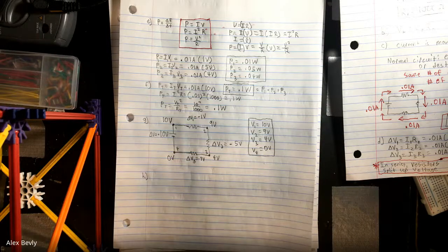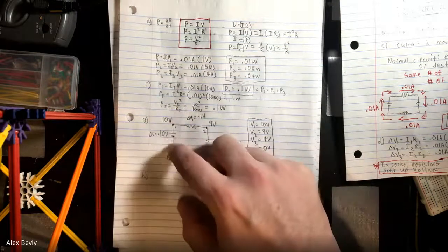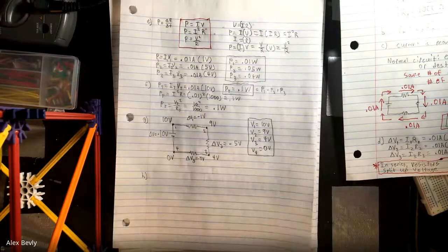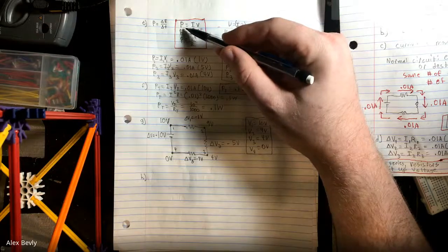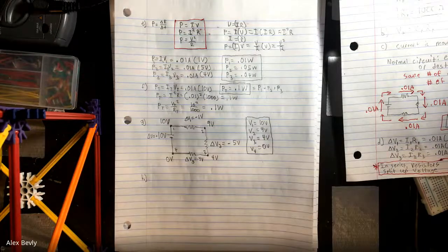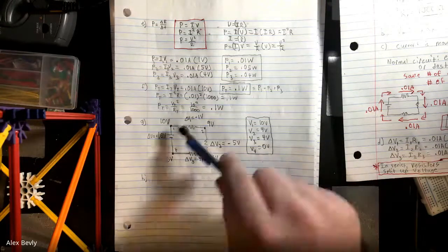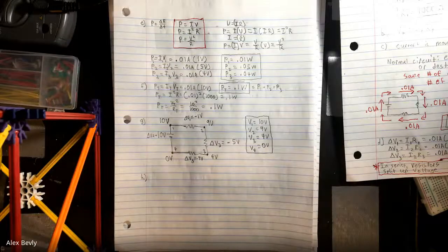Yeah, it's bad to touch both ends of the battery. If you touch both ends of the battery, you just have wire to wire. The wire has a really low resistance. So if you have a low resistance, you get a really high current, and a really high current means a really high power. Most of the energy is going into heat. So things get really hot and you can start fires, or the battery itself could burst once it gets too hot. So yeah, don't short out batteries.